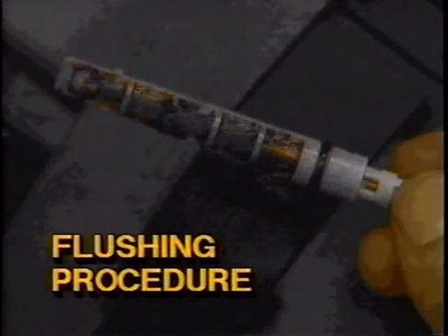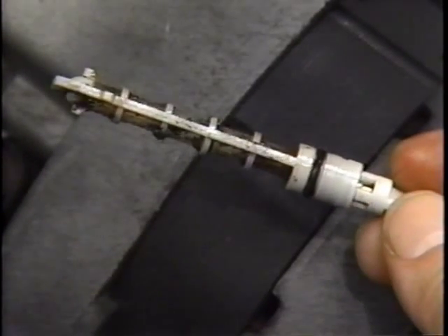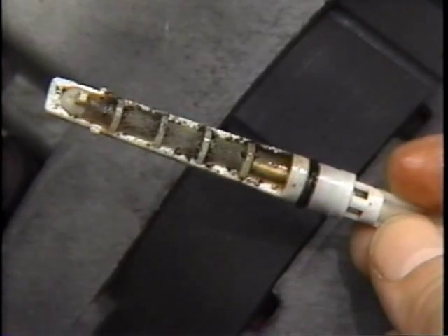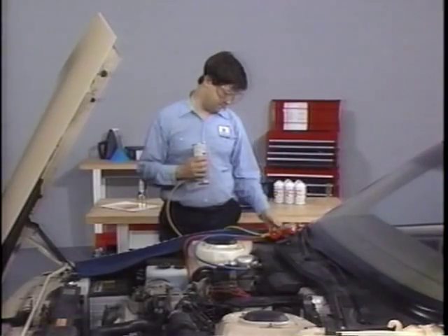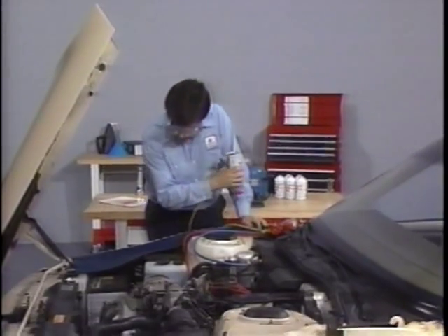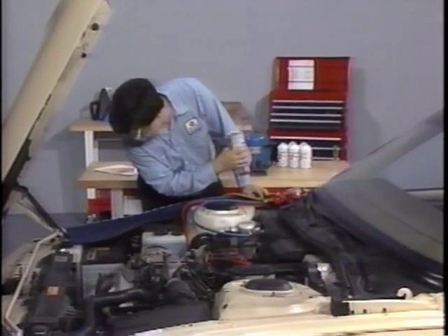If the air conditioning system has been opened to the air, it will have to be evacuated and charged. If the system has been contaminated with metal particles from a seized compressor or with other foreign matter, you will have to flush the system. We'll cover the procedures for flushing and recharging using disposable cans of R12. The procedure is similar when using large drums of refrigerant.